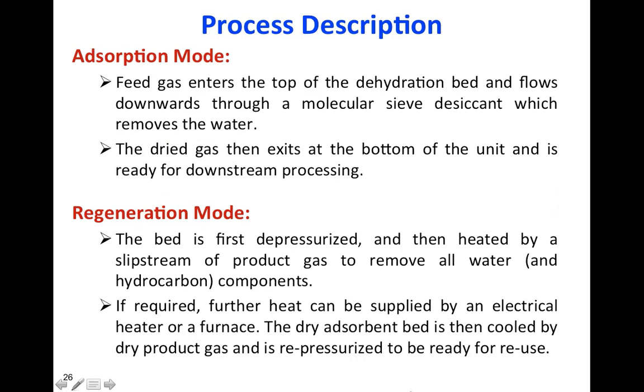Then, okay, just a few more slides to finish this part. For the adsorption mode, I already explained this, but I will repeat it here. In the adsorption mode, my feed gas goes to the top of the dehydration bed, and it goes down. It can be a molecular sieve. Molecular sieve means the bed. So I have my bed.